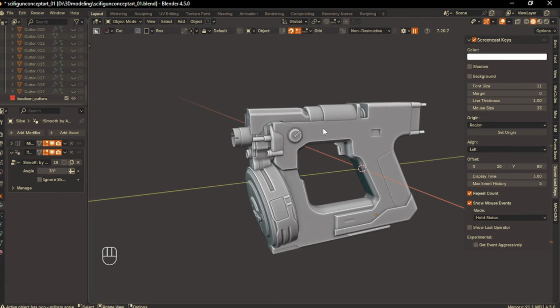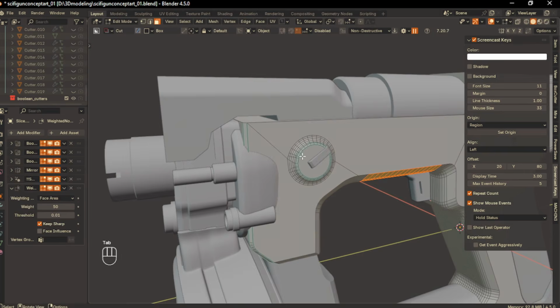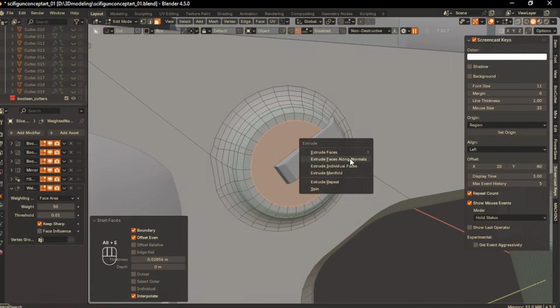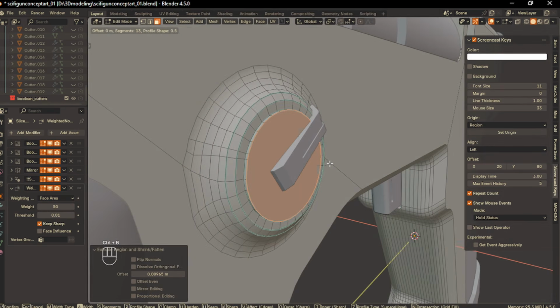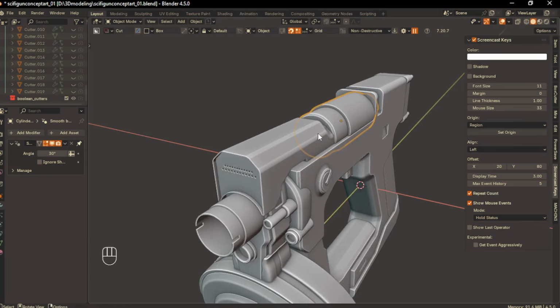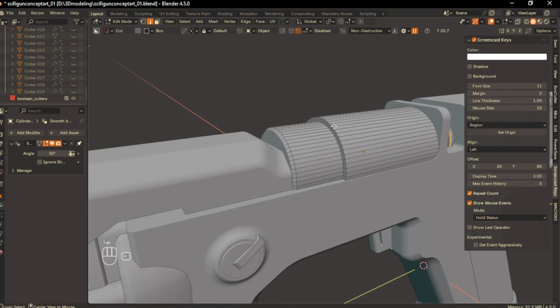Now let's refine the cylinder shape. I'll go into face mode, insert this face, extrude it just a little, very small, and then run a small chamfer for that nice highlight. That's clean. And finally, I'm going to add a chamfer to the top cylinder too, just to soften those hard edges.